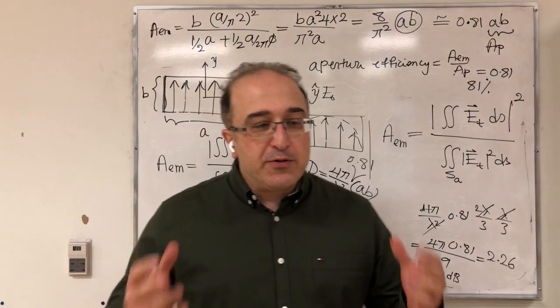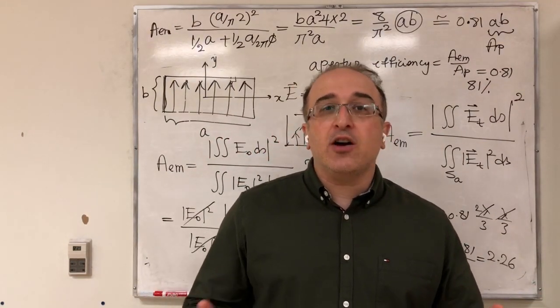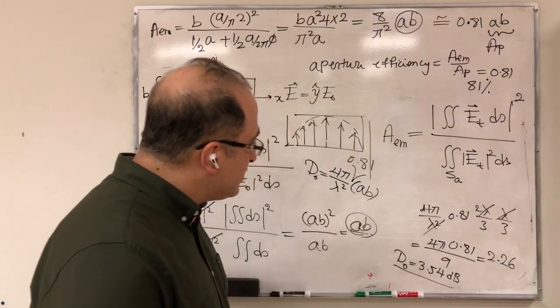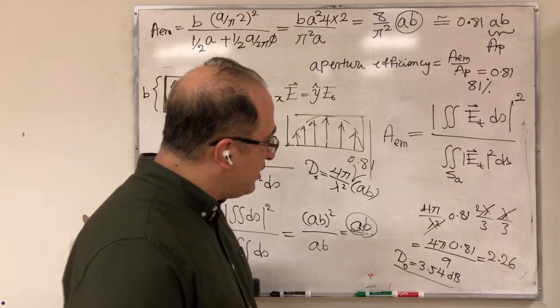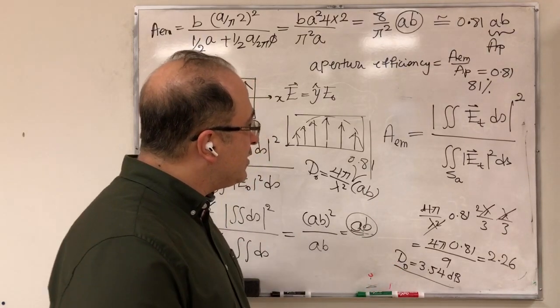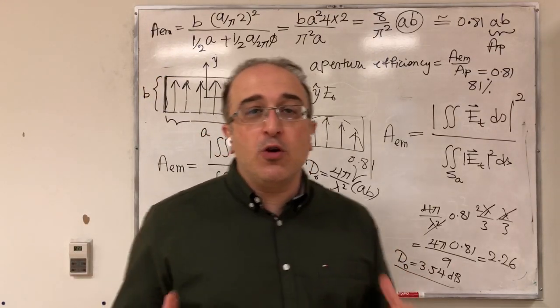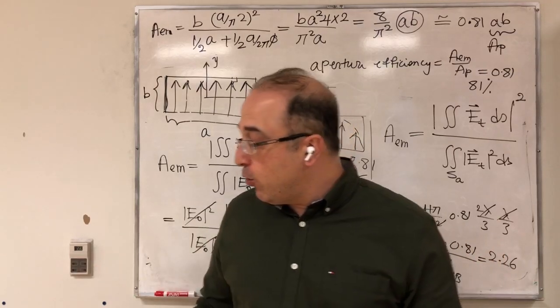Okay, so we've seen that the role of aperture is very important in getting higher directivity. Now, we want to increase our directivity because, with open-ended waveguide, this is the typical directivity that we have, 3.5 dB, and so we want to increase the directivity, and this is the way to go. This is essentially the reason that we have horn antenna.